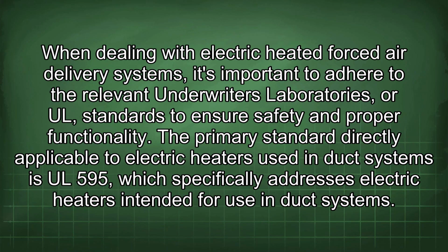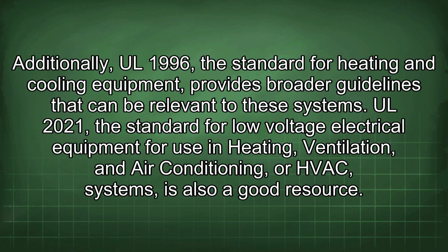When dealing with electric heated forced air delivery systems, it's important to adhere to the relevant Underwriters Laboratories, or UL, standards to ensure safety and proper functionality. The primary standard directly applicable to electric heaters used in duct systems is UL 595, which specifically addresses electric heaters intended for use in duct systems. Additionally, UL 1996, the standard for heating and cooling equipment, provides broader guidelines that can be relevant to these systems.